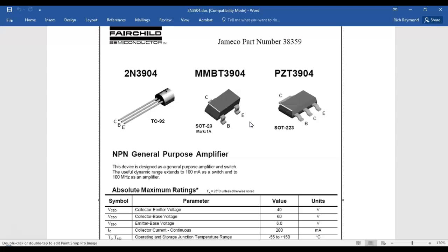So if I had a 3-lead device, like a voltage regulator, a triac, or a DIAC, instead of designing my own transistor case, I could use this, and the molds and everything are already out there. We have all these standard cases. What's nice about a standard case is that I can use an application to design a printed circuit board and do all the spacing and hole placement for me. But that's only if I use what? Standard cases.